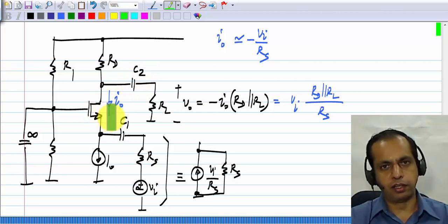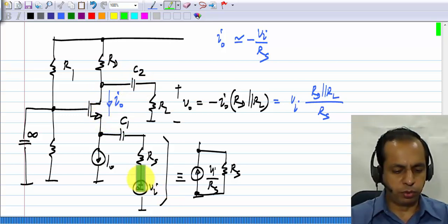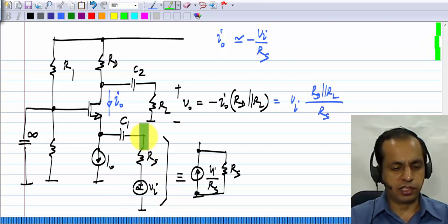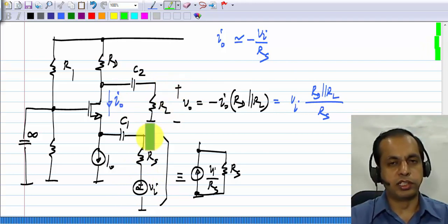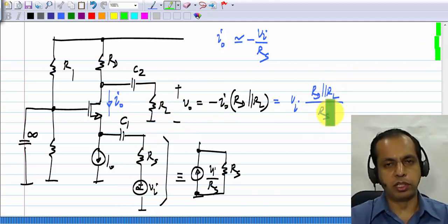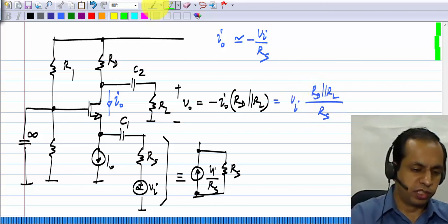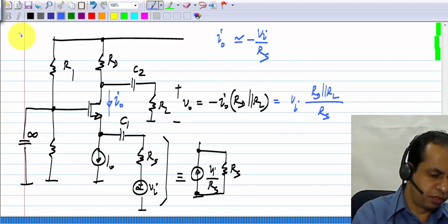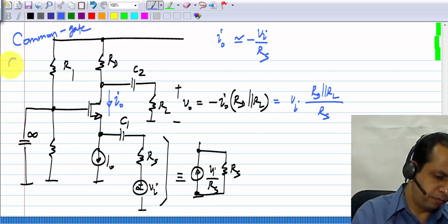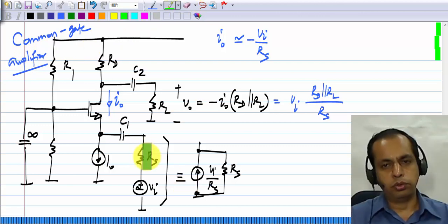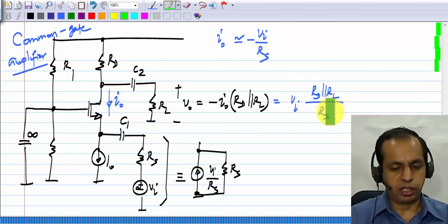So this is really a current controlled current source, but you can operate it with a voltage source in series with a resistance, and also consider the voltage as the output. Okay, in that case the gain will be some resistor ratio, which can also be accurately set, and it is sometimes used like this. Okay, so when you see this common gate amplifier, you do see it sometimes with a voltage input, and the gain is this one.